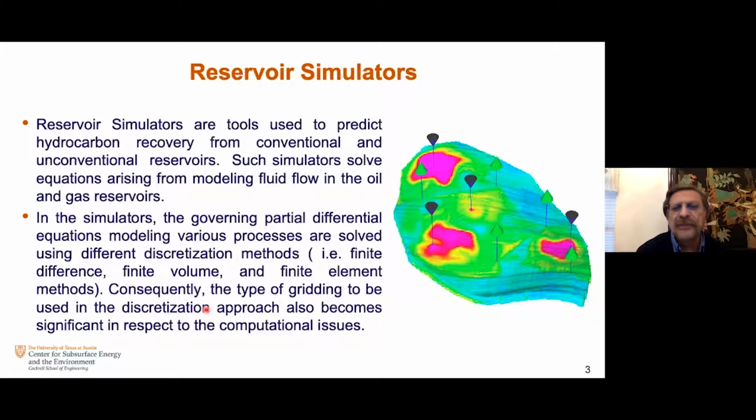The governing partial differential equations are discretized using techniques such as finite differences, finite volume, and finite element methods. Because we are using grid-based discretization, the gridding becomes important, as well as the accuracy of the methods used for discretization.